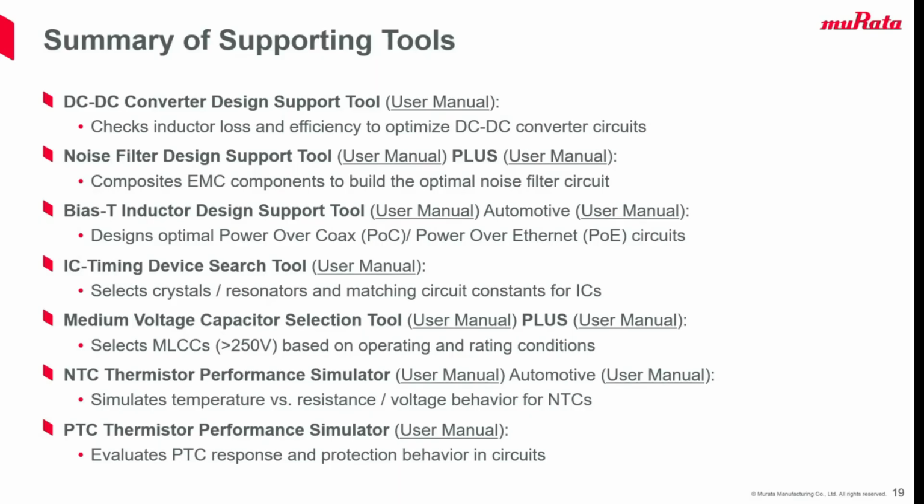This is used for temperature sensing or compensation applications, and it allows you to simulate how resistance changes with temperature given a specific circuit. For the positive temperature coefficient thermistor, we also have a performance simulator where you can test for things in, say, a protection application where you want to see current limiting or resettable fusing specs on a specific PTC where resistance increases under faulty conditions. You can easily visualize that within this tool.